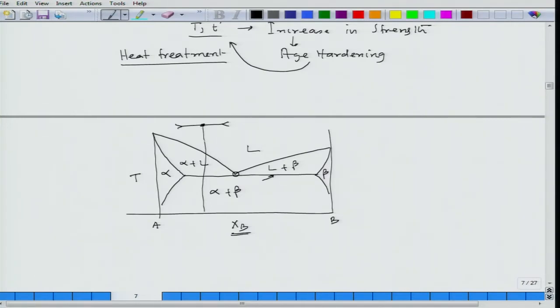But as the temperature drops, at a certain point it will touch this solid liquid phase line, which is nothing but the equilibrium between solid solution and liquid solution, and at that time I could get the first alpha phase, a sprinkle of little small nuclei of alpha phase.